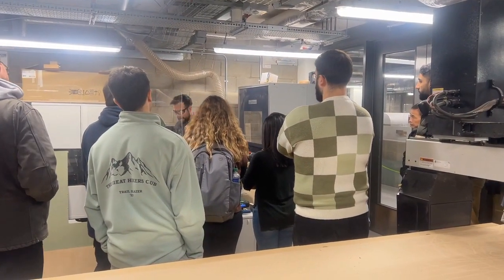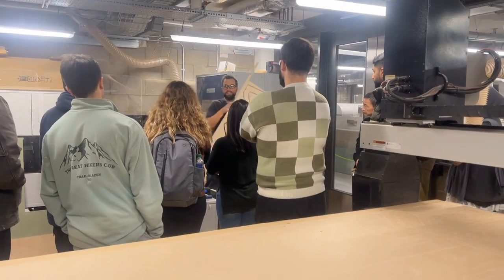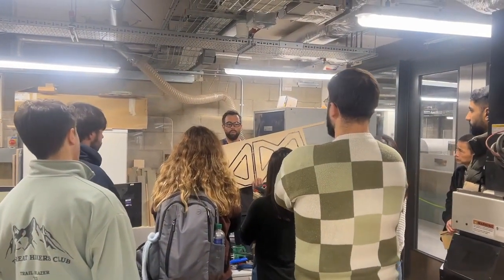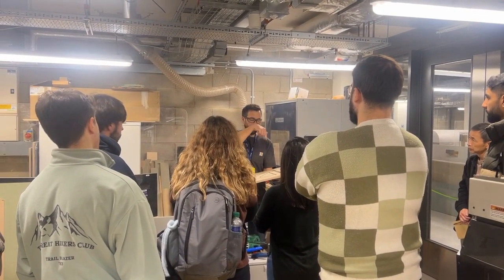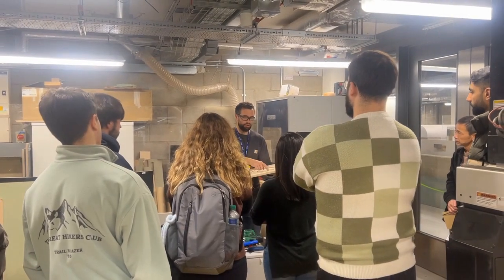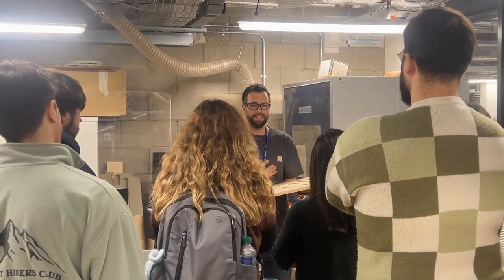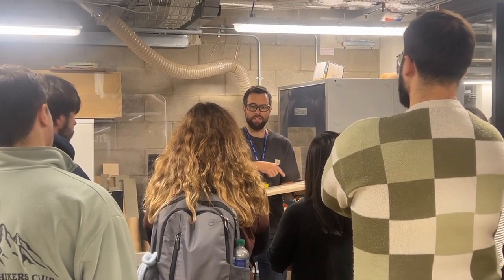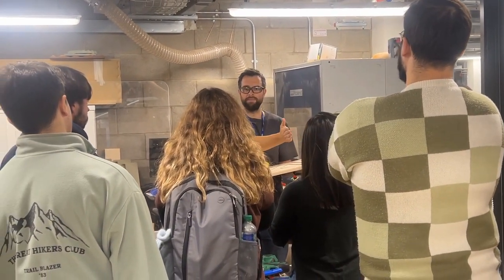Right? You can get a 2.5D outcome from the CNC router using 2-dimensional vectors. Now, what that is, if you can communicate what's going on from a plan view, essentially they are then boundaries. These are vectors that are boundaries, and we can interpret those boundaries and cut inside, outside, or on if they're a continuous loop. If it's a singular line, you can only ever cut on the centre of that line.